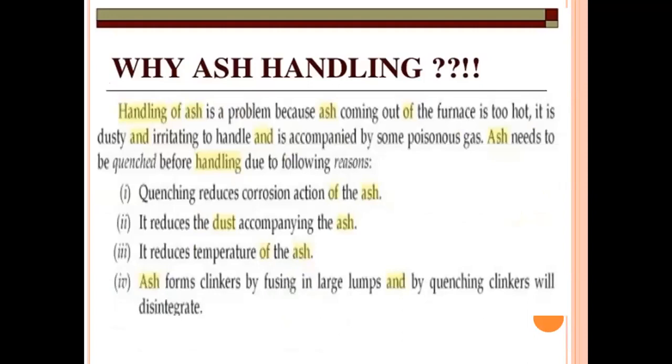So why ash handling? Handling of ash is a problem because ash coming out of the furnace is too hot, it is dusty and irritating to handle and is accompanied by some poisonous gases. Ash needs to be quenched before handling for the following reasons. Quenching reduces corrosion action of the ash. It reduces dust accompanying the ash. It reduces temperature of the ash.